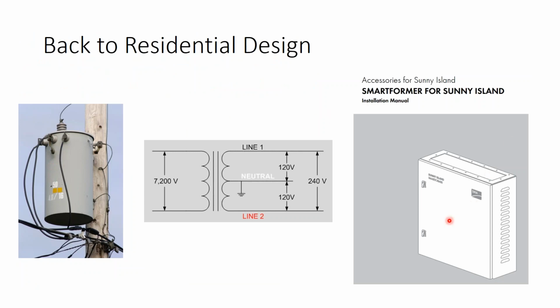The SMA battery inverter is a 120 volt output. And so you might need to buy a transformer to get it to 240 volt output. Or you could do a 120 volt output on each leg and get rid of the transformer. But then if one of the two inverters fails, you're out of luck. You don't have any backup for that. So you might need to buy additional transformers.